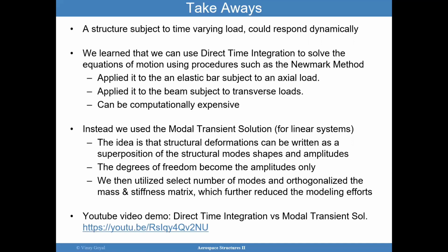We demonstrated that if I had a whole rocket and I wanted to solve it for the whole rocket, say I have a rocket that's made up of millions of degrees of freedom, or an aircraft, that it would be computationally expensive to use the direct time integration procedure. So while we used it and demonstrated its success, another approach that could be used is a modal transient solution, which could be very beneficial for linear systems.